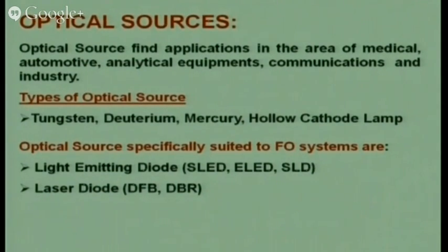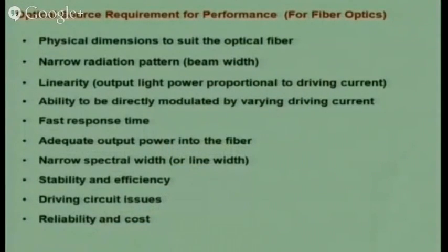We will be discussing all these concepts of LEDs and sources one by one, and why we need so many varieties of sources within LEDs and within laser diodes. The basic requirement for the performance of any fiber optic system or analytical system is its compatibility with the system. It can be a fiber system or an analytical system. The physical dimension of the LED or source should match the optical fiber, because the course is on optical fiber, so it should suit the physical dimension of the fiber.